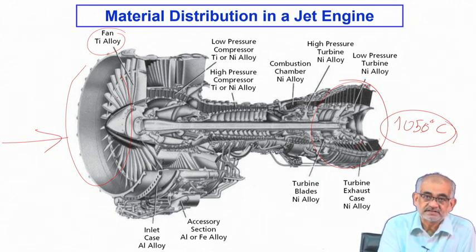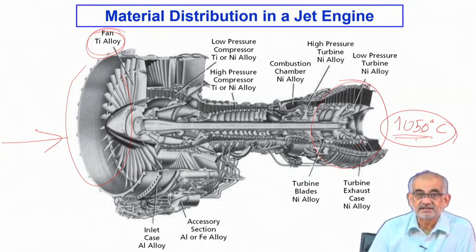So the turbine blades undergo very severe hits from the sand particles or whatever particles get sucked in. So these titanium alloys should have sufficient erosion resistance, right? Here, apart from erosion, because by now you don't expect so many particles to flow all the way there, you certainly expect much higher temperature and high temperature attack. So you have to take care of the thermal fatigue, the creep damage, because you are subjecting it to elevated temperature at constant load, and most importantly oxidation at that temperature.